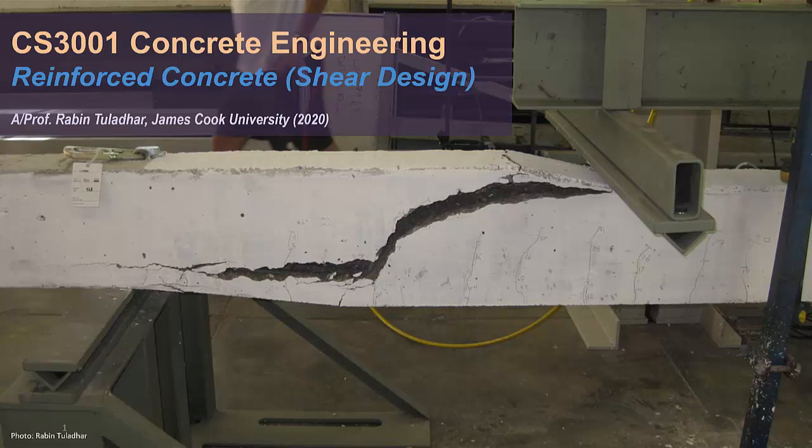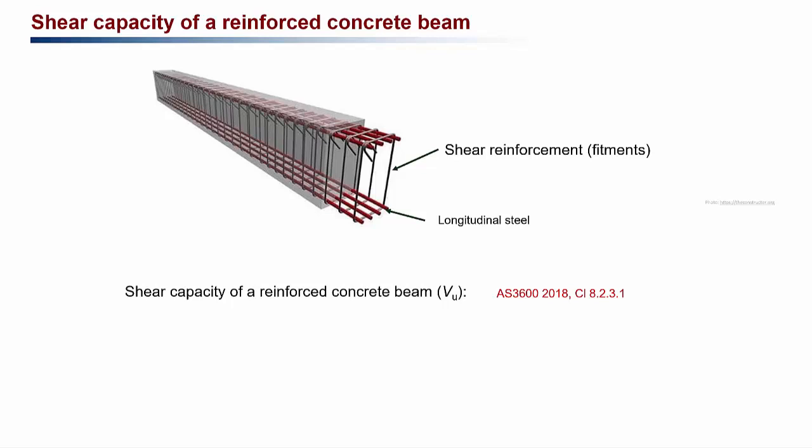This video covers the shear design of reinforced concrete beams. For the reinforced concrete beam, we have longitudinal reinforcement in the tension side, and if it is a doubly reinforced beam, we can have a longitudinal reinforcement in the compression side as well, as we see in this beam.